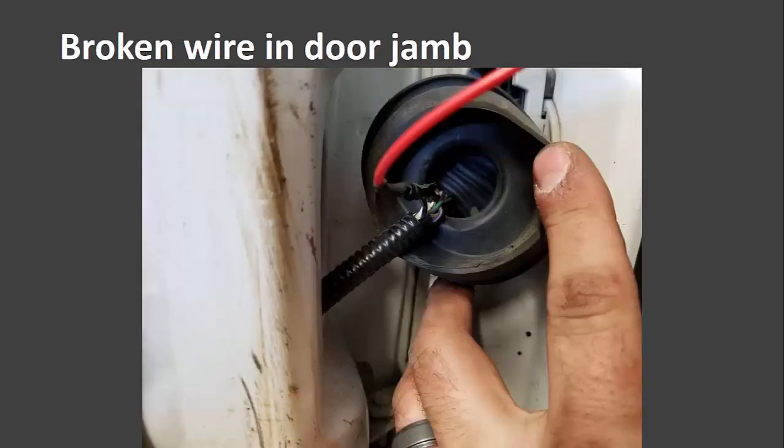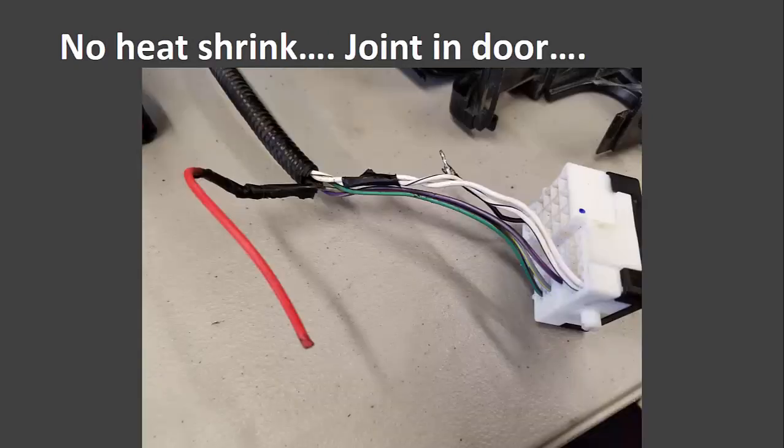So I pop the boot back and I find a broken wire. Someone had already been in here and soldered a little wire in. The issue is, A, their soldering joint was in the door jamb, so as the door flexes, it's going to be hard on that joint. And B, they didn't even heat shrink it. So there was some corrosion built up, and that's kind of why the wire broke off as well.